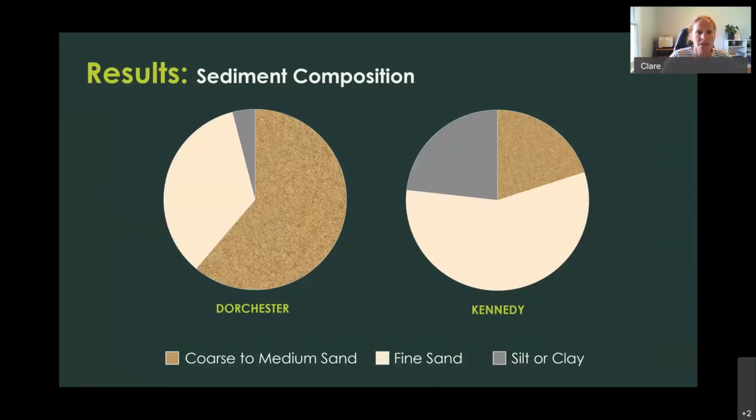You get a higher pH, you get lower redox conditions, all factors that promote SRP release. So while we often think about the sediment composition being important for infiltration through these bioretention systems, our field data shows that it's also really important if we're going to use these systems for phosphorus removal.